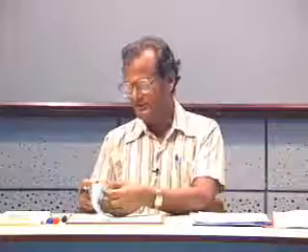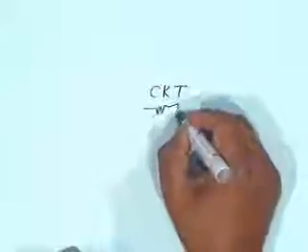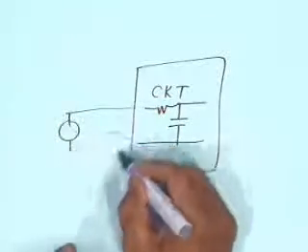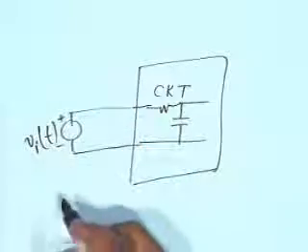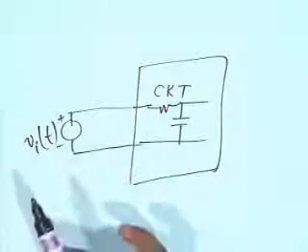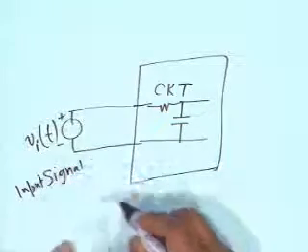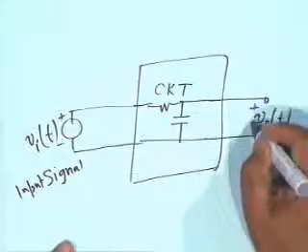Now, a very common system that you have already been familiar with is an electric circuit. Electric circuit, for example, a simple RC circuit, let's say like this. Well, this is a system. It receives an input. Let's say you apply a voltage source here, VI(t). This is the functional form. VI is the function and t is the independent variable, a function of time. This is a signal called the input signal, and then you produce from this an output signal which could also be a voltage V0(t).